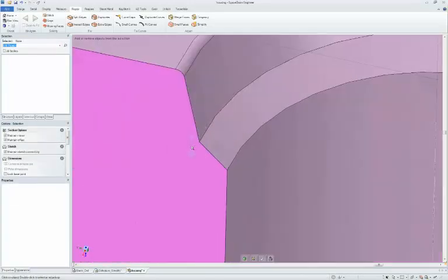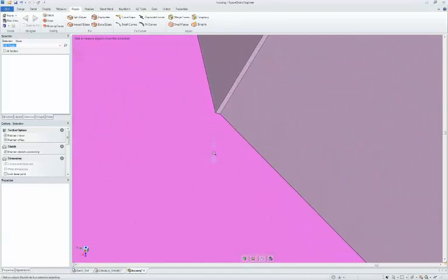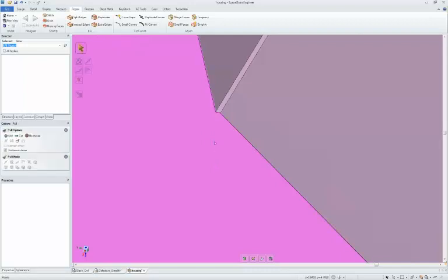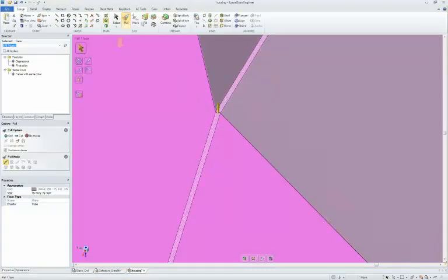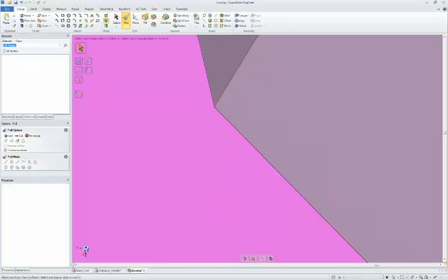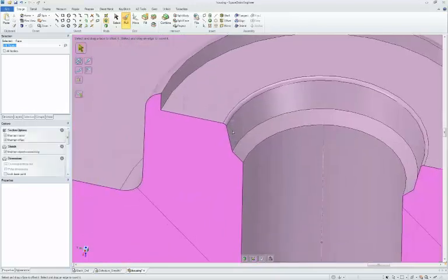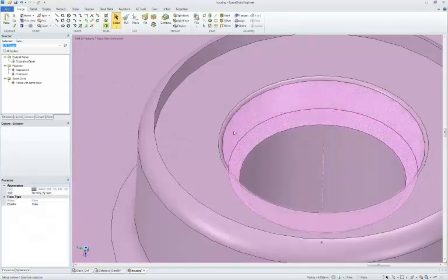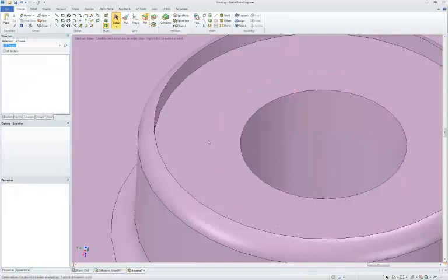If I go into a cross-section and I zoom in, this is that face that was there. It's such a small face on the model, on the design, this can definitely cause an issue in meshing. This is why I like to be able to select these faces. You can see it in the cross-section. Fill eliminates it. Fill brings it to that sharp. Gets rid of these potential problem areas. And in fact, if we want to go through and eliminate all of these, same thing. Same tool lets me select and fill to eliminate them.